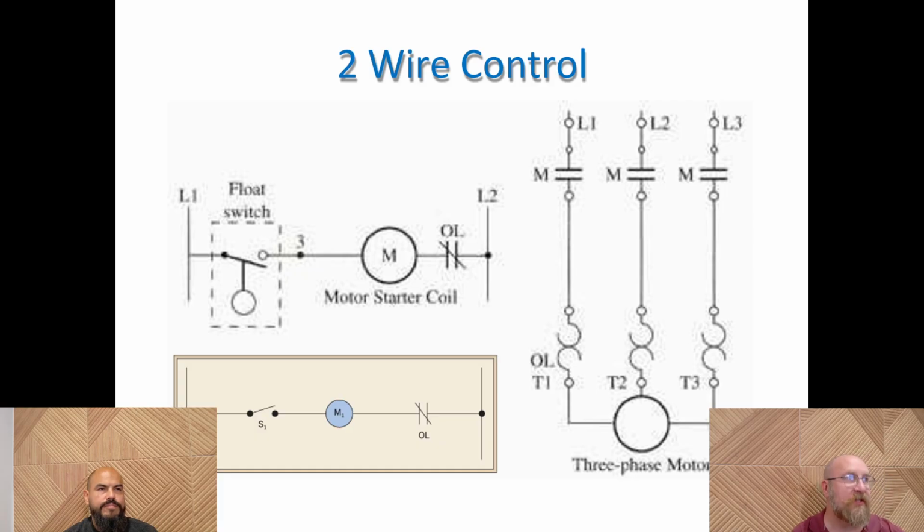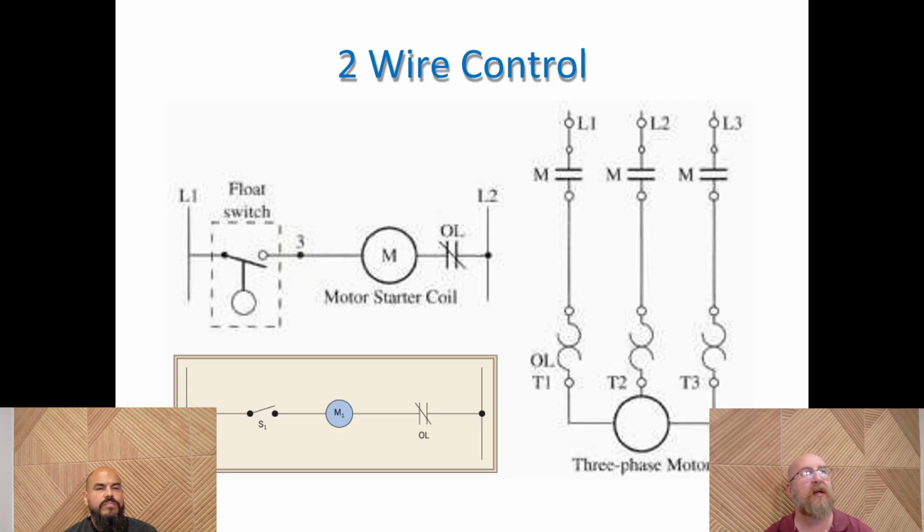It physically looks like what you see on the screen there, because when those curls of metal heat up, they curl back on themselves tighter, and so that breaks the connection. And then when they cool off, they make contact again.